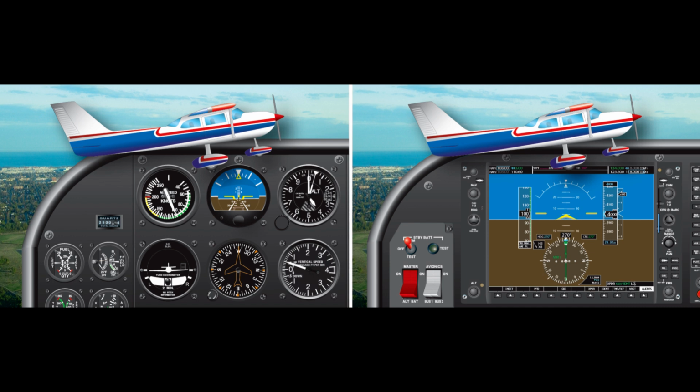Compensation for the inherent stability of the airplane, overbanking tendencies, adverse yaw, propeller effects, reduction of the vertical component of lift, and increased drag needs to be managed by the pilot through the manipulation of the flight controls. Climbing turns may be established by entering the climb first and then banking into the turn, or climbing and turning simultaneously. During climbing turns, as in any turn, the loss of vertical lift should be compensated by an increase in